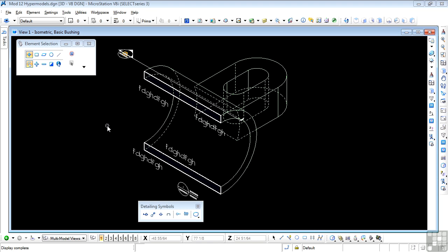A marker can be used to link information other than sections or elevations. This includes links to other files and documents, and even links to web pages. Final plotting and printing composition is made by referencing the various saved views and models into a title block reference. You control the presentation display of the references in, of course, the references settings box. Reference saved views display their markers, and naturally, update if the model clip volume is updated. Now, since hypermodels are an extension of the fitted section tools, you can manipulate the clip volume and the location of the callouts using the same techniques.